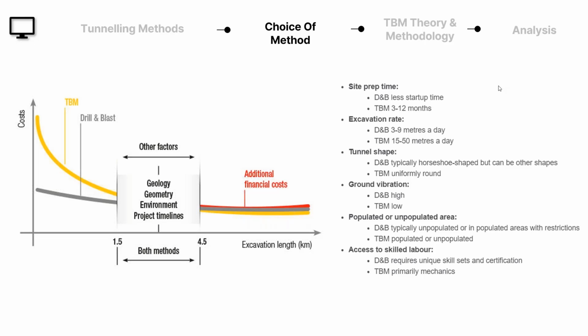Coming to ground vibration. We all know that with blasting, the vibrations will be high. So yes, in this aspect, drill and blast will have greater vibration. That is why the peak particle velocity is normally checked before blasting in any area. You have firms like Orica or Dyno Nobel which do these kinds of studies, and they will come back to you and let you know what kind of explosives to be used for blasting in any particular area. Because with the PPV issue, it is critical for areas which have high population density or urban areas.